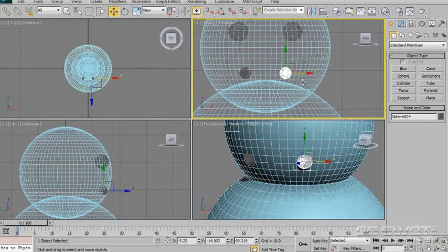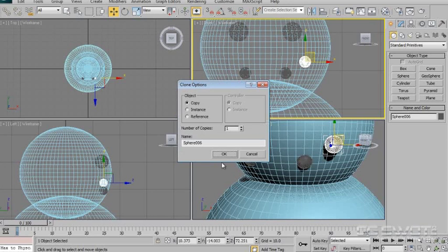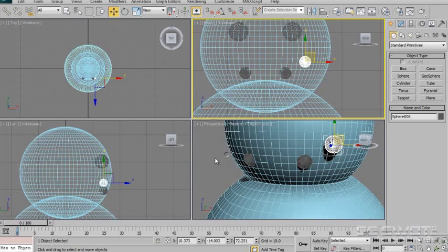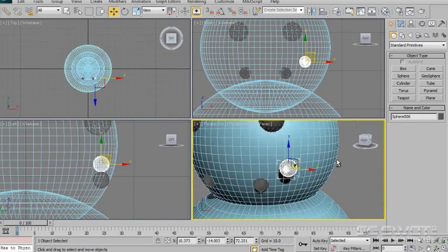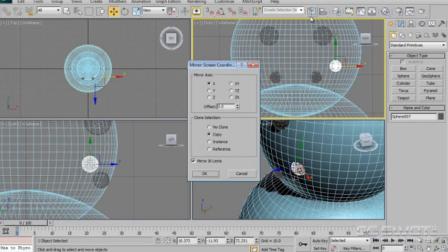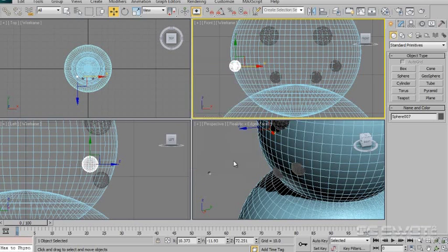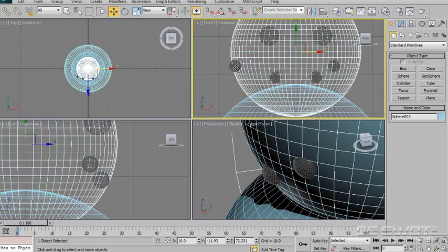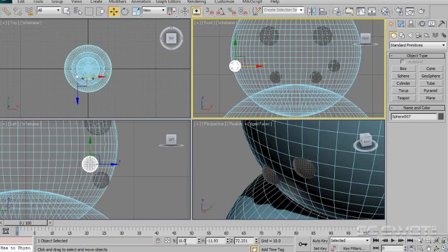Same method again, just grab this one here, only this time we're going to move it in 2 axes. So I'm holding down shift and I'm dragging it up, and on 2 axes means I can move up and down and left and right. So I'm just going to pop it probably about there, and it's a copy. So we go OK, and I'm just looking at my perspective view here, and I'm moving it in that left view. Something like that looks okay. And then we can mirror that in the front view. Just drag it over, eyeball it, we'll just make this a nice round figure. Let's make it 10. We'll just make sure that still looks okay in that viewport. Yep, looks fine. So this one here should be -10.